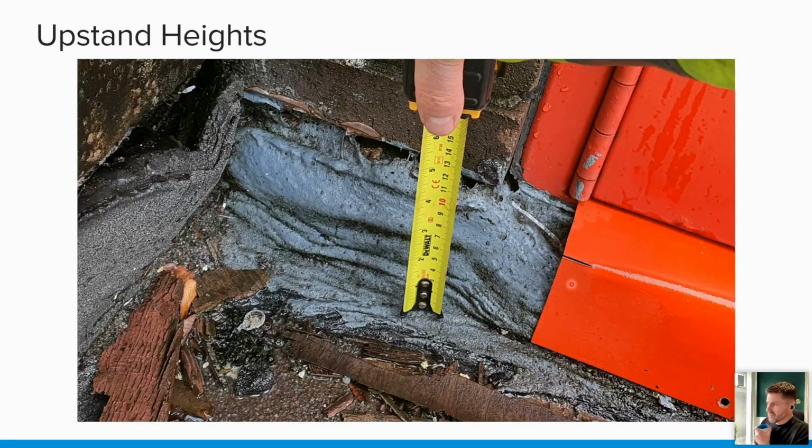If the door can't be replaced, if the threshold can't be raised, all those kinds of things, then all of those things need to be raised with the manufacturer who's putting the specification together, because it's up to them then whether they will guarantee this door threshold here, or whether they'll exclude that from the guarantee and maybe put in that it's a maintenance item and needs to be checked every 12 months or something like that. We can see as well in this instance, we've got a bit of ponding water here, so we might need to do something to adjust the falls on this roof and get this water to be falling away from the upstand. So all things we need to be considering when we're surveying the roof.